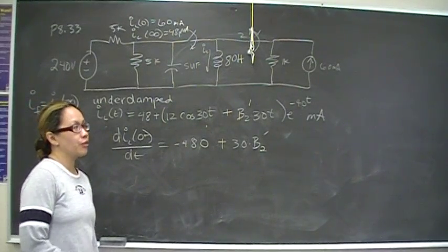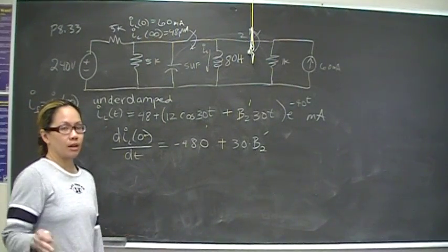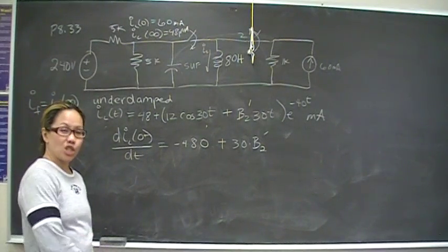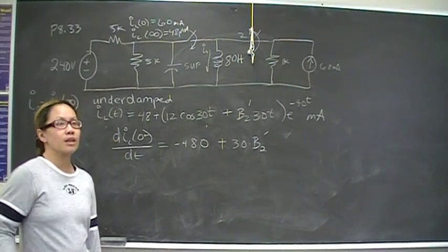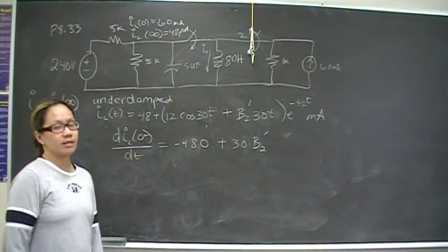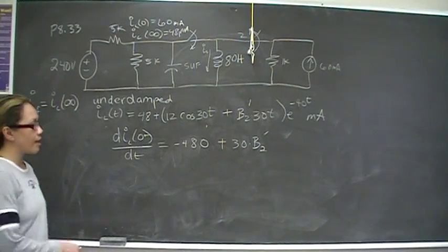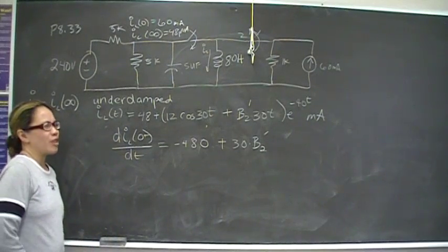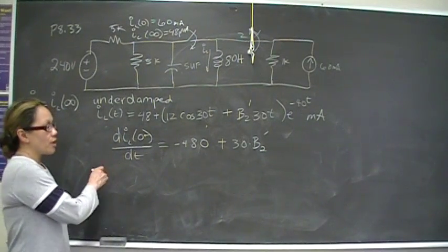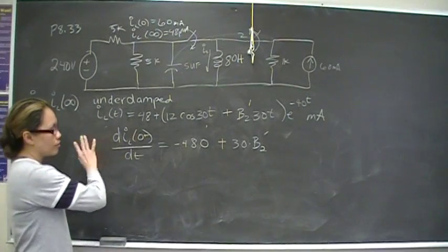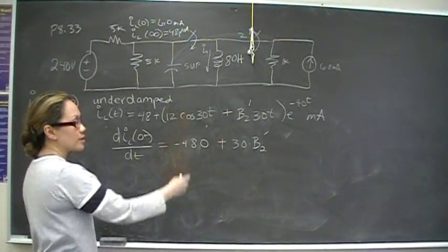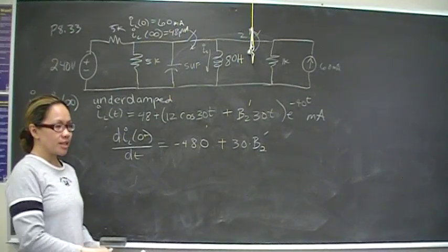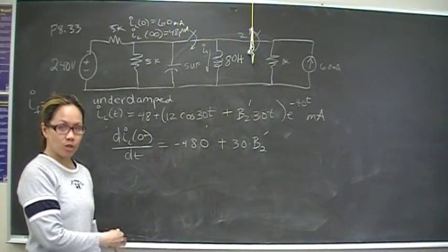You have voltage, dVc of the capacitor. You have to look at the fact that the capacitor can't change voltage instantaneously, but it can change current instantaneously. So if you're looking at the inductor, you have to look at the inductor equations, but we're solving for inductor currents, so the dx dt, what is that? That's going to come from the set of equations for the inductor.